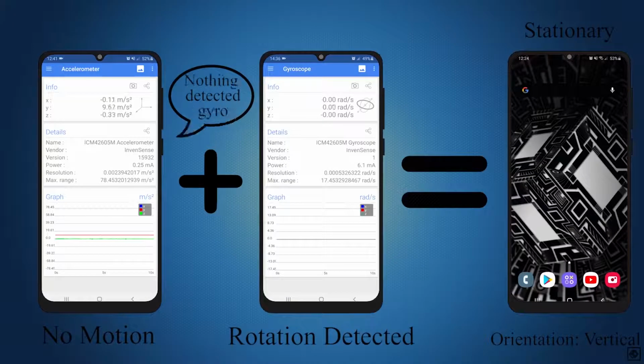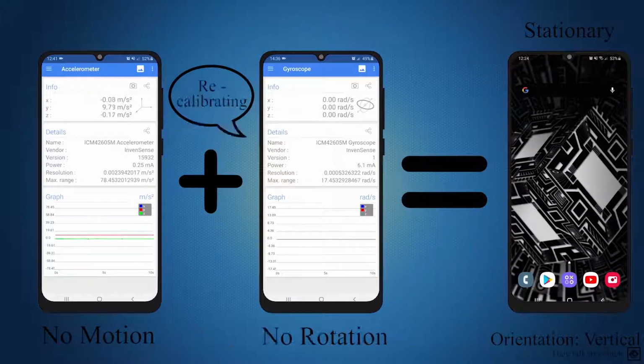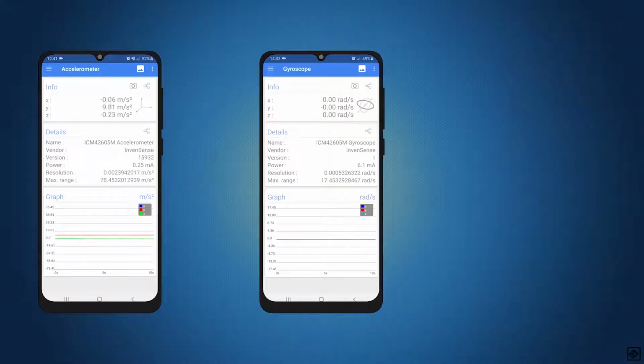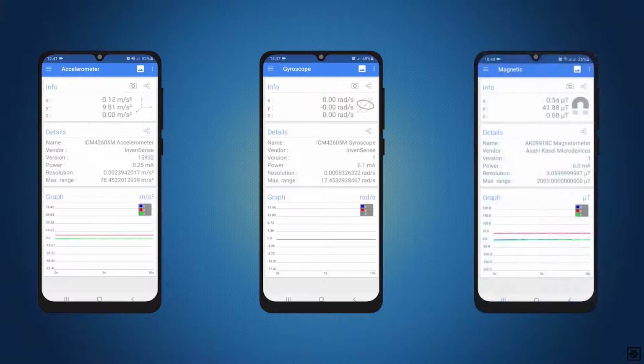Similarly, the accelerometer can be used to recalibrate the reference frame of the gyroscope and get a more correct and consistent rotation. Whenever the device is at rest, the output of the accelerometer equals the gravity vector. And drift can be periodically corrected by using the gravity vector from the accelerometer. With these 2 sensors, we use one more for the orientation of the phone.